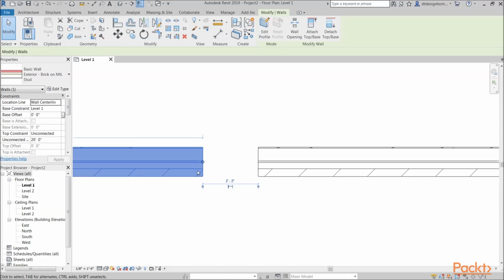Now, if this thickness exterior changes, because this has to remain the center point, what's going to happen is it's going to shrink. Let's say this shrinks by 2 inches, just as a rough kind of measurement there. If the entire wall is shrinking by 2-inch overall thickness, we're going to shrink an inch here and we're going to shrink an inch here to keep that location center line on the center of the thickness of the wall.